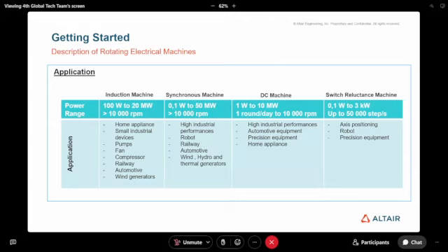Concerning our machine today, as I told you, it's called the synchronous reluctance machine, and the stator is exactly like a permanent magnet synchronous machine, where we have three phases, and it's exactly the same kind of stator and winding. But for the rotor, there are really plenty of configurations. I will focus mainly on radial lamination and axial lamination.